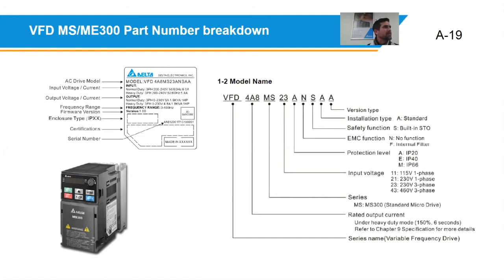And then the second question is from Mike. Do all the drives have a communication protocol such as Modbus? That is a very good question, and I don't think I've mentioned that in the slide. All the Delta drives have built-in Modbus. Every single drive, from the most economical all the way through to the high-end drives, have built-in Modbus. In fact, the pump purpose drives, the CFP and the CP2000, also have built-in BACnet communication for BMS systems.